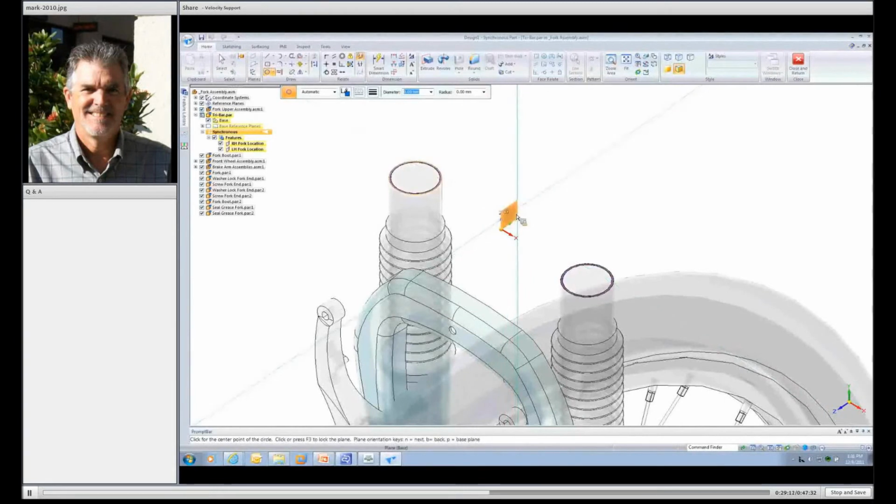And I want to place one more for the center bar. And then I'm going to change my value to 40 millimeters, or 20 millimeter radius. And I'm going to find the center of both of these side ones again. And then I'm going to change the diameter value to 60. And I'm going to place that. Now you'll notice it's beginning to build regions. The closed shapes of the circle will build the regions for us.